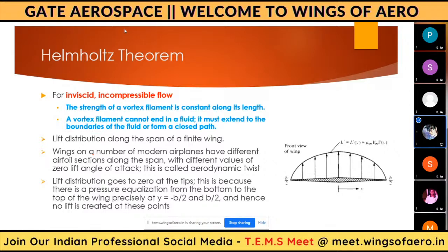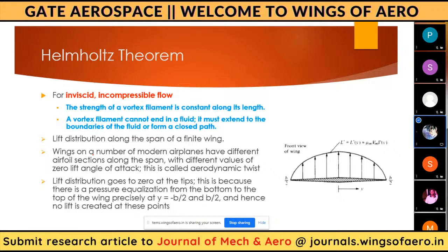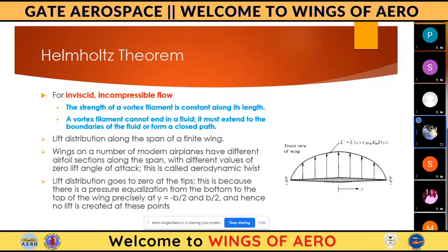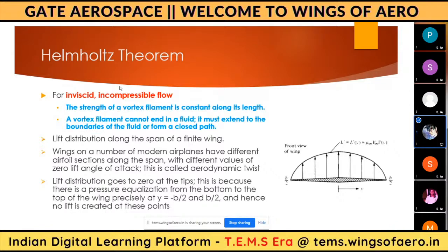What we will do now, we will be meshing. We will create a boundary. First we will be creating a boundary for low speed aerofoils and all. We will be creating a C-shaped control volume, not a boundary layer, a control volume. So a C-shaped control volume we will be making.